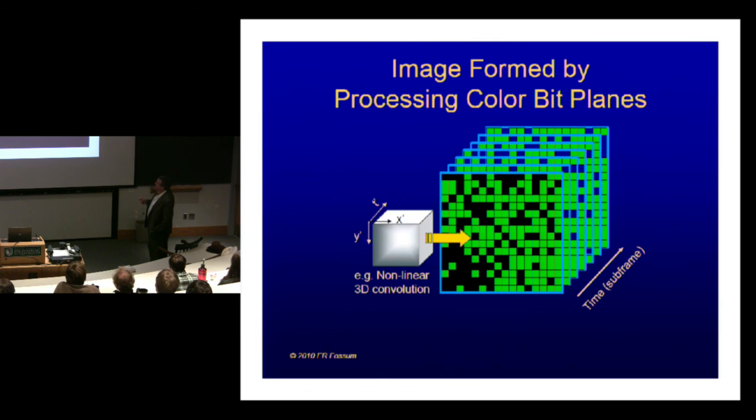And a lot of interesting things with this, which I guess you'll have to take my word for, but one of the things you can see right away is, if we change the size of this convolution window, we can immediately trade the resolution of the image, because it's going to be about that size, against sensitivity. So if we increase this up, we can capture a lot more jots in the processing, but with a lot less resolution. So it's a little bit like film. We have big grain film that's very fast, and very fine grain film that's very slow. But here we can do it a priori. We already know what the result is and then adjust the convolution window to get the optimum result.